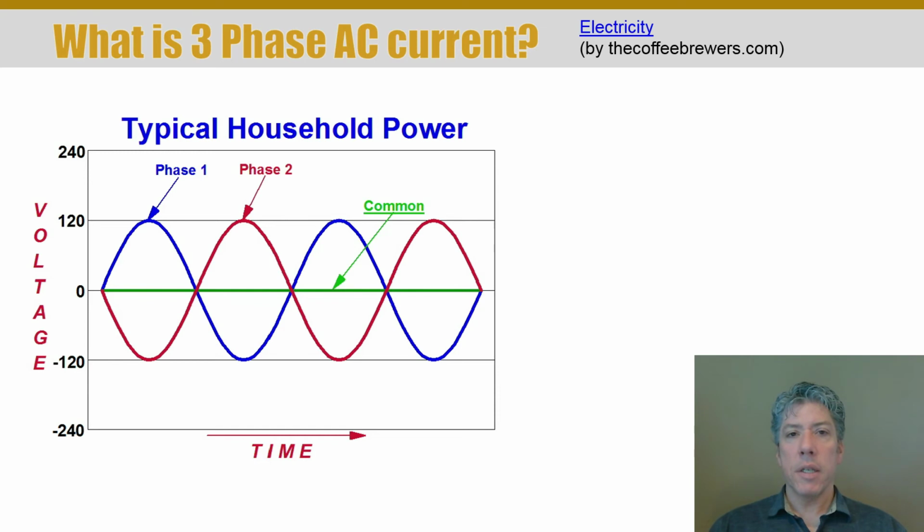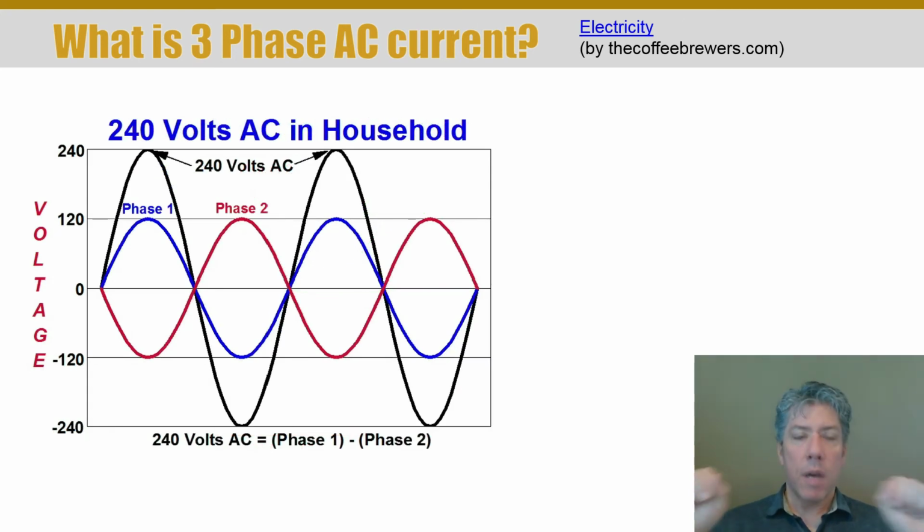So this is 120 volt AC. Okay, that's each leg is 120 volt AC. But if you measure the difference between those two hot legs, then that's where 240 volt AC comes from. So you may or may not realize that there are two out of phase hot legs coming into your home from the transformer. And a lot of times when the power goes out, everything's just out, right? I mean, you turn on any light switch, nothing works.